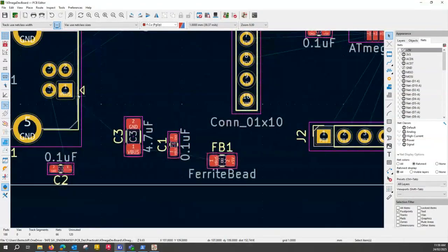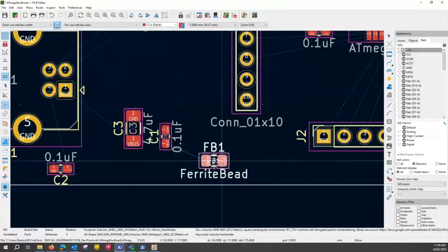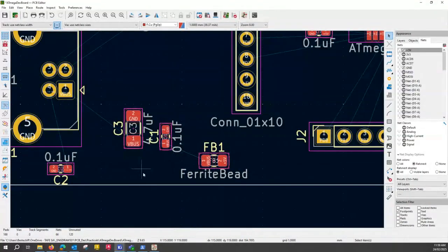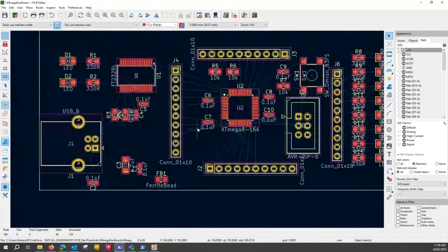What else do we have? We've got our V-bus, which has to come down somehow and run across through this chip there. I'll make this up a little bit. This one across, maybe. We'll see what will happen. This connector here, that's fine. I'm just a little bit mindful of space.